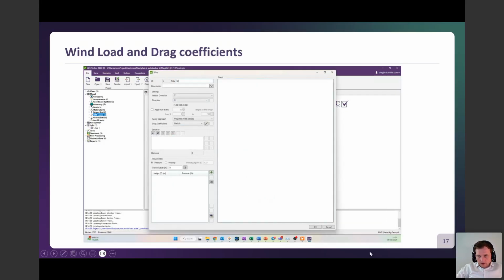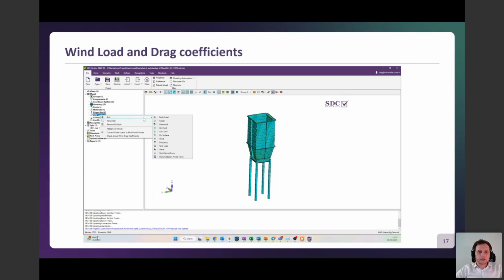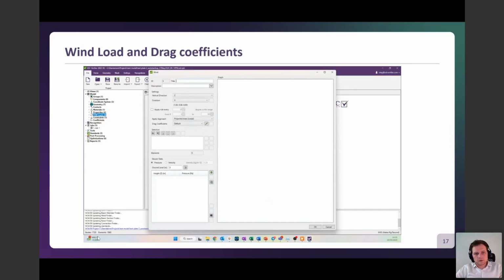And for all of those tools, what you would have to do is go into the interface of F.E.M loads, I'll start it from scratch, execute right click, add, and then you select from different types of loads. You select wind profile, give it a name, let's say in this case wind in X direction, define the vertical direction of your model and direction of wind.